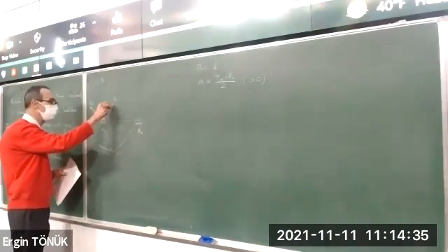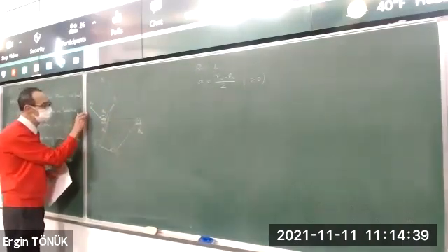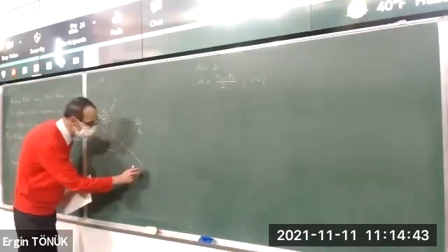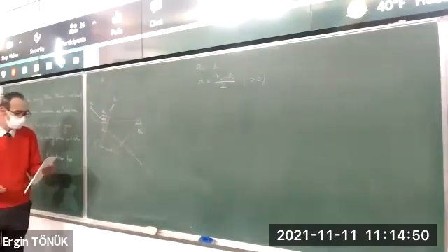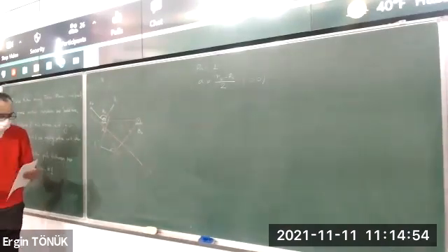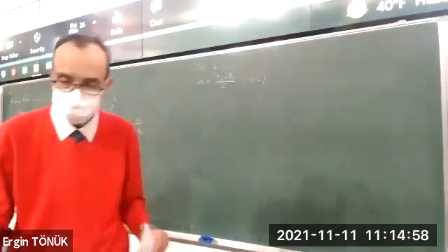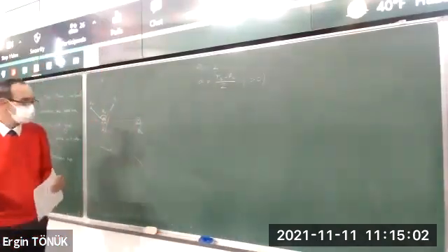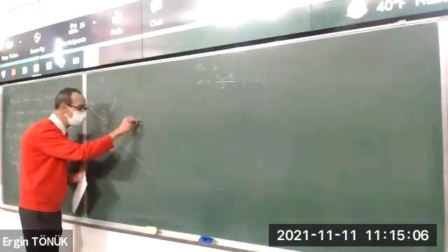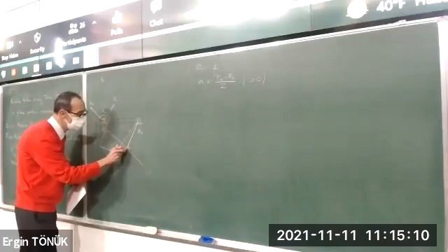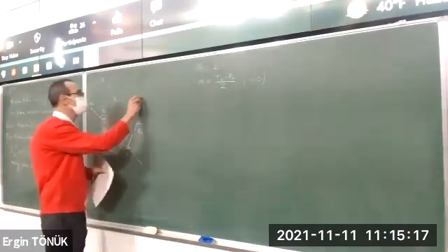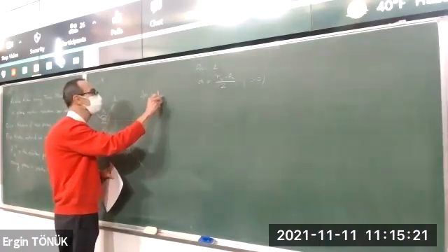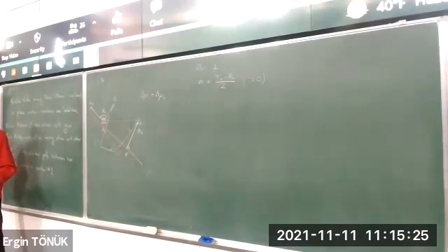So I have to draw the perpendicular bisector like this. Let's call it A1 to 1. Okay, so you can select B1 anywhere on this line. All points are candidate. But if you want the transmission angle deviation from 90 degrees to be equal at the two extremes, just drop a perpendicular to this and select B1 here. In that case, delta mu1 would be equal to delta mu2. But it doesn't say that delta mu would be small. Okay, we have no control on this.